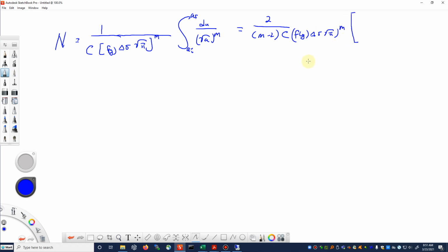And then instead of writing this as the final minus the initial, we're going to write this as the initial minus the final to take into account the negative sign that I'm not writing in here. If this doesn't make sense, just do the integral and you'll see where all these terms come from. We have 1 over the initial crack size, on the bottom, m minus 2 over 2. And then we have minus 1 over the final crack size, m minus 2 over 2.